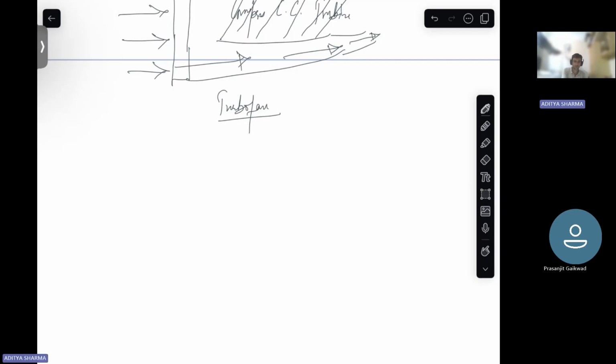Then turbofan works up to around 10,000 meters, and Mach ranges between 0.5 to 1. And for turbojets, you have a high Mach range, as per lecture 5 from 2.5 to 3, and the altitudes at which this can work are also pretty high, in the range of 20,000 meters. This is the comparison between these three types of engines.